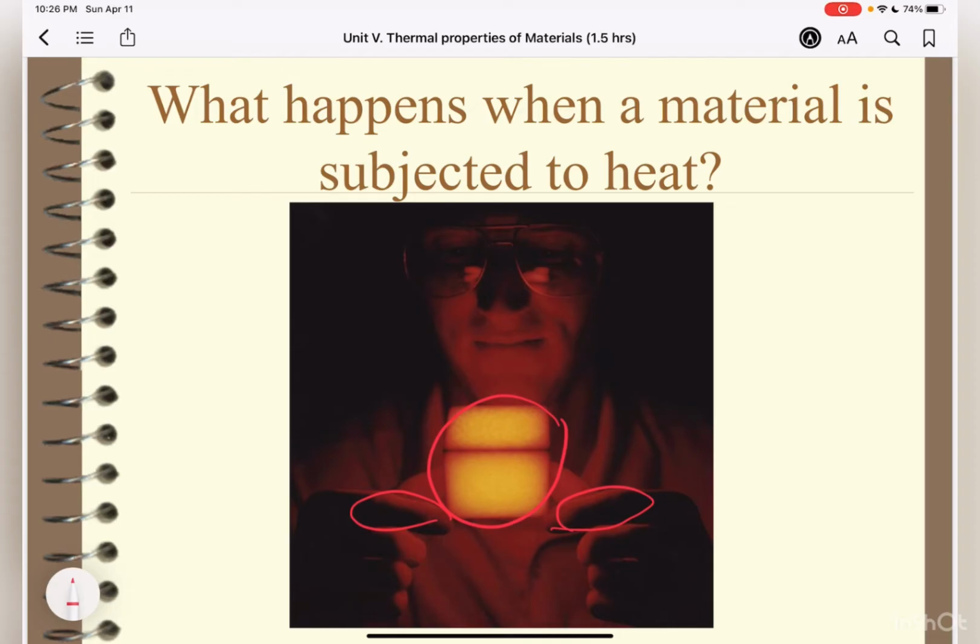So what transpired here? Initially, the heat transfer from the surface is relatively rapid. However, the thermal conductivity of this material is so small that heat conduction from the interior to the exterior is very, very small, such that the maximum temperature is approximately 1250. But take a look, it can be held by a bare hand because, as I've said a while back, the thermal conductivity is so small that heat conduction from the interior to the exterior is so slow.